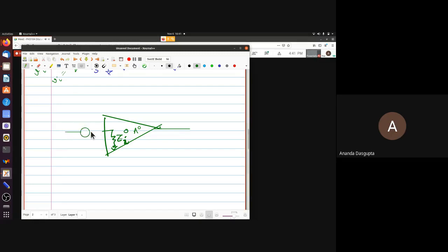So let me point out what's going to happen. You have an input. Well, X here, since we are talking about voltage to voltage amplifiers explicitly, let's no longer keep it that abstract. Let's call this Vi, and call the output Vo. So this was what we were calling X before, and this is what we were calling Y before. Because we are now specializing to voltage amplifiers, this is the input voltage, that's the output voltage, and a fraction beta of the output voltage is taken and fed back to the input in such a way.